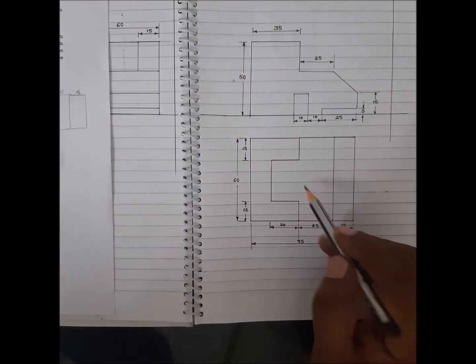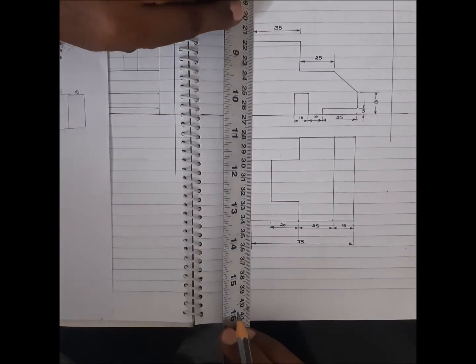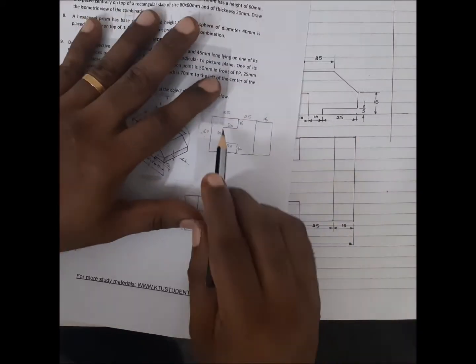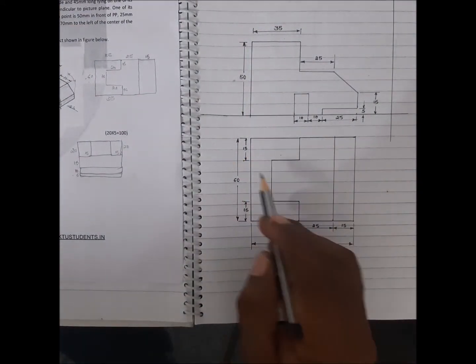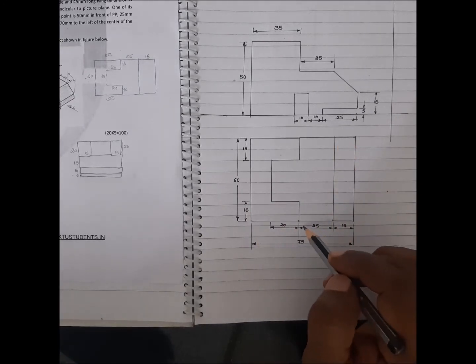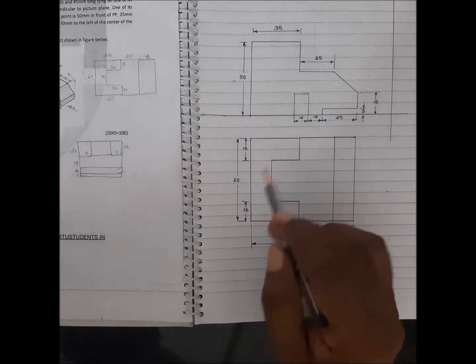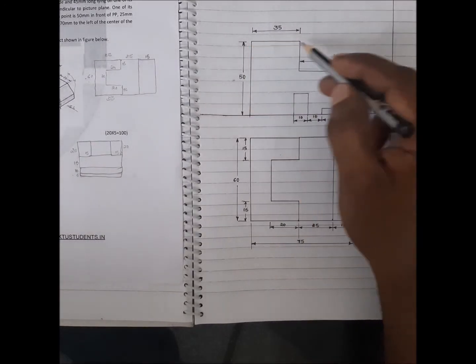So what I've done here, I just started with the top view first, then I make sure that all these projectors are on the same line. Draw the XY line, start with the top view. You can just start with the top view as we have done here, rough sketch here, a 60, 75 rectangle, and inside that you can make this 15, 25, 28, this line of 15, 15. Again, it's not a big deal. You can make the top view drawing and you can extend these lines, and 50, 35, 25 you can make this drawing. That's not a big deal.